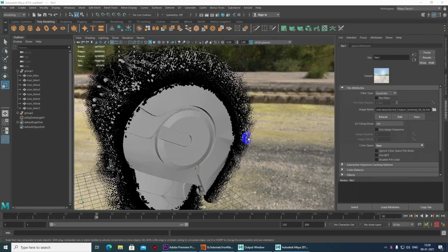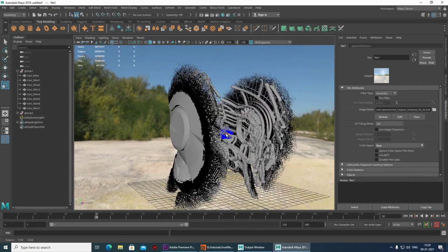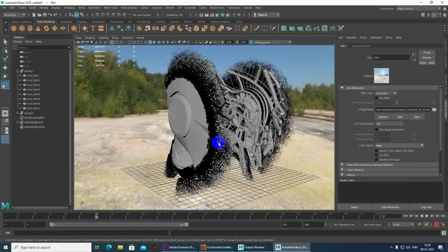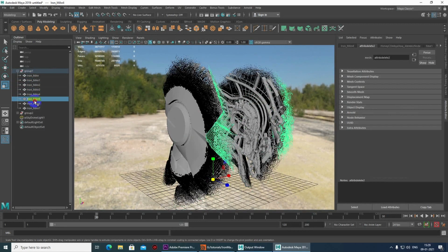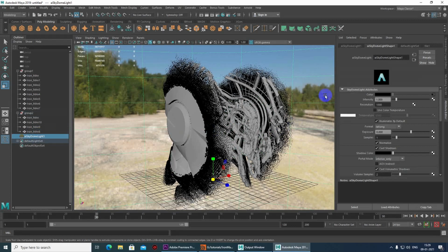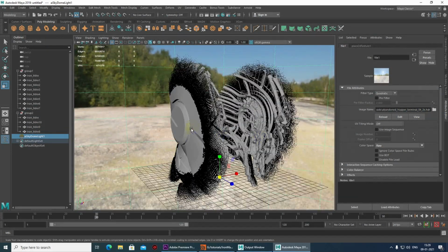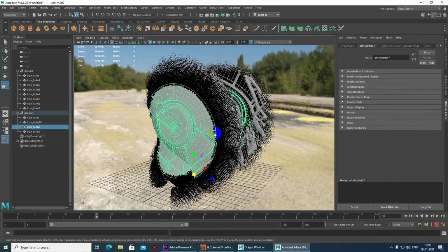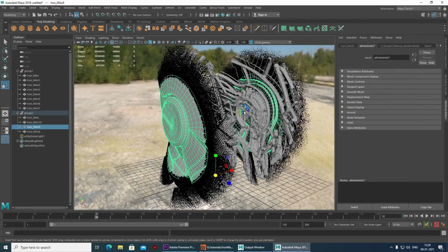Hello guys, in this part of the tutorial I will show you how I rendered it with the help of Arnold. So for that I have very quickly imported all the cached out Alembic geometry, and now there is a basic lighting, like I have used a sky dome light, and I have inserted an HDR map. So now as we have exported with group, I have already made the texture of this Arnold shader.